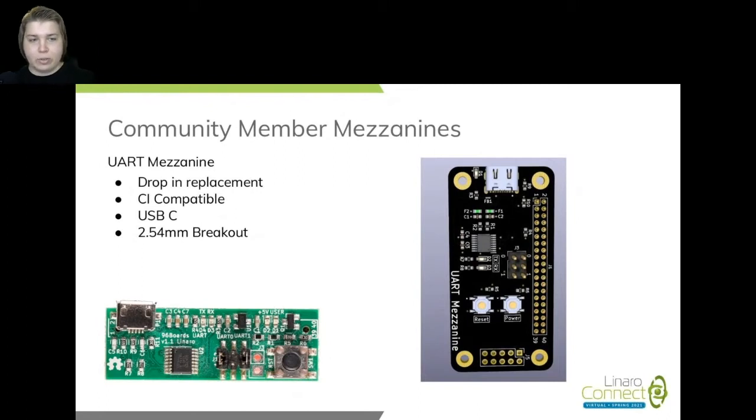I've also especially been working on a UART Mezzanine to replace the old UART Mezzanine that was designed back in 2015, as those aren't very available anymore and needed an upgrade anyway. So I've been building an open source board in KiCad, as you can see in the rendering on the right. It will be a drop-in replacement, so you can just stack it and you don't really have to change anything.